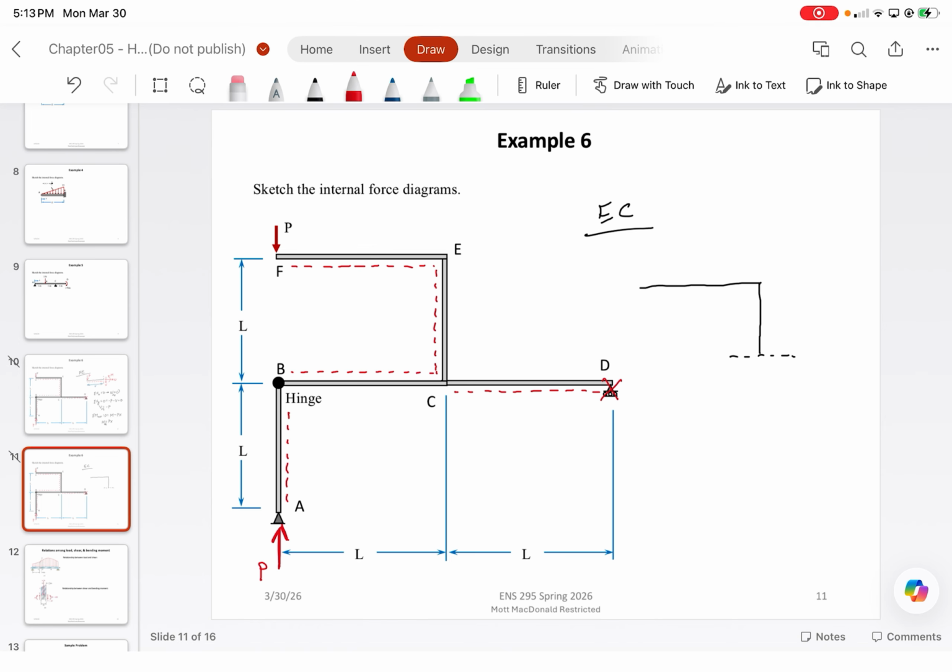Don't forget about your force P. But now, what's our function going to look like? Is that when you have a value for the axial load, it's going to be negative P? Exactly. But what I'm asking is, all of our equations, we know that this dimension here is dimension L, right? Which means that all of our equations that we develop are going to be with respect to this dimension, which we can call y.